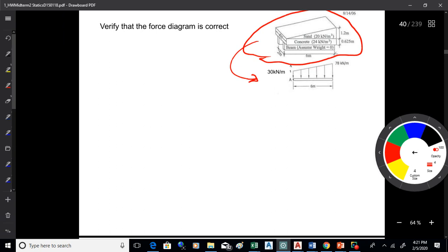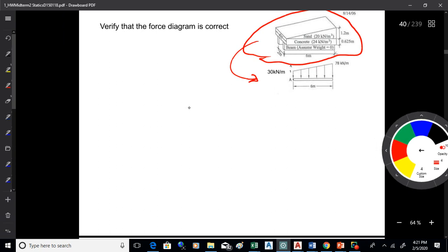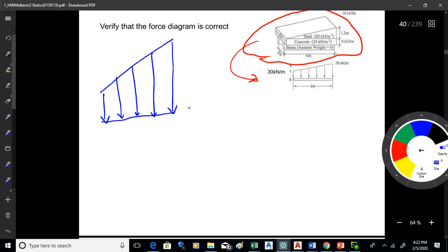All right. Now, what's happening here is we've got a trapezoidal load, right? So we've got something going on like that. Now, if you look at how those materials are configured, how they're put together, what I can see there is I've got a diagram like that. The concrete has a constant width, so I think that's going to get us a constant load. And then the sand starts at 0 and angles up from there, so I think that's going to get us a triangular load.